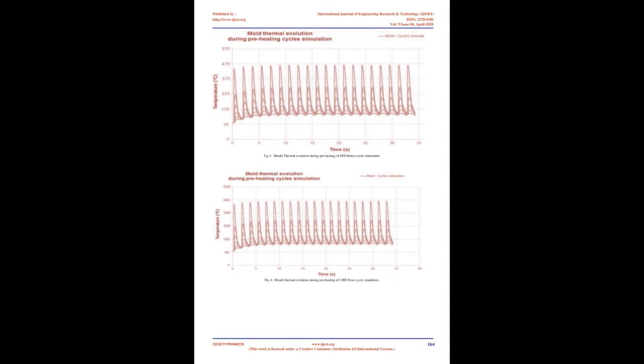Preheat temperature. Preheating in gravity die casting is done to remove the possibility of the formation of temperature gradients. If we increase the preheat temperature beyond a particular range, it may affect the die coating and create defects like rough surface finish. Also, if the temperature is reduced considerably, this may cause a chilling effect, which in turn leads to less solidification of the core, and due to this difference in solidification rate, defects like solidification shrinkage may occur. A significant precondition for the production of high-quality castings is keeping an optimum temperature of the respective parts of the mold cavity surfaces.